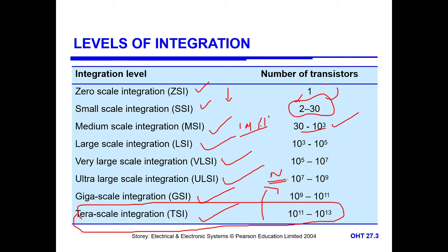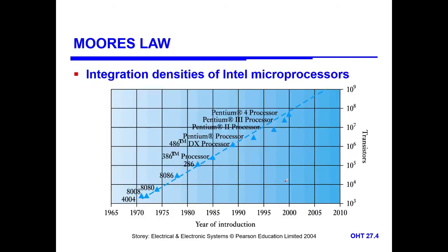Between the source and the drain, the channel allows only a single electron at a time. Using that single electron we get the current, and that current is capable of achieving the function we have been getting by making use of the various integration levels. So we can get the same function with a single electron transistor also. That is the present research area happening all over the world.